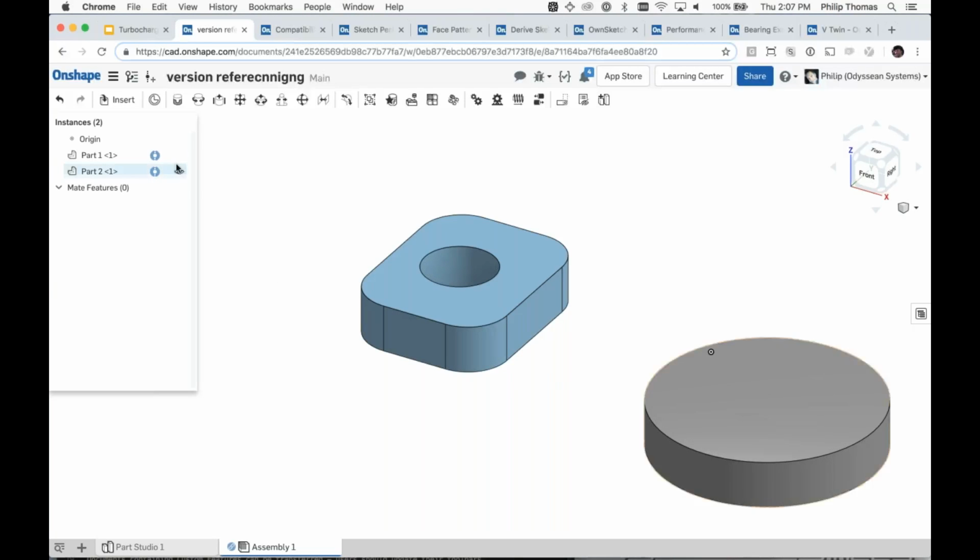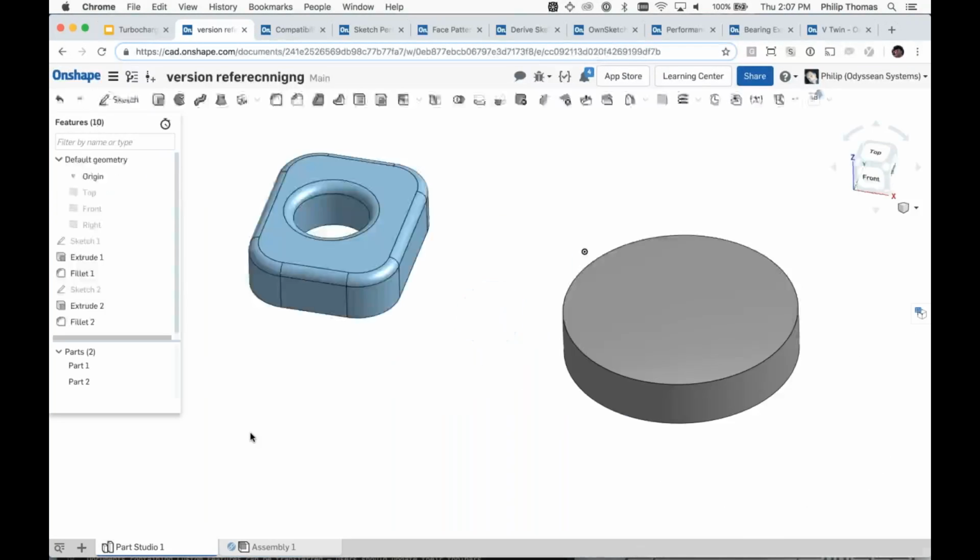So this is where I tell you you're going to want to use revisioning because you'll get so many false positives, especially for standard parts documents where you might have a lot of part studios, a lot of parts in it. In order to make a new part available to the organization, you either have to make it not rev managed or you have to version the entire document. It is actually much better to use release management and just rev this.